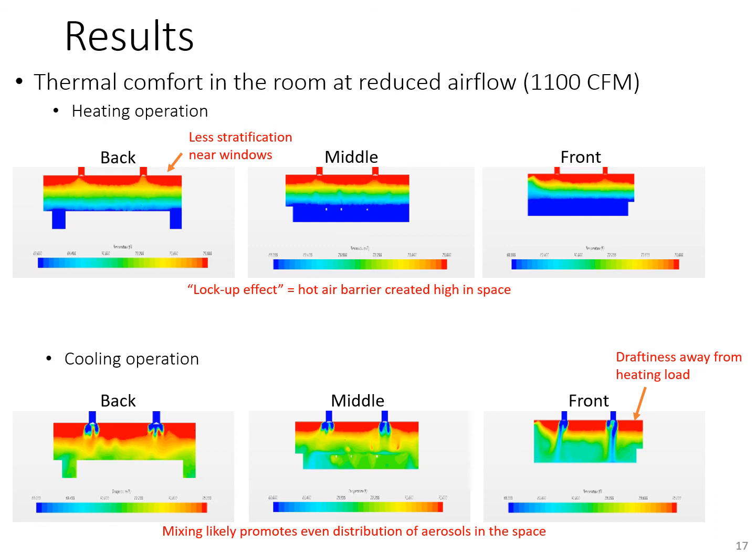First, the warm air of the space was not provided with enough CFM to reduce thermal stratification and push the warm air closer to the students. Thus, you would likely still have very cold zones near the students' legs and feet. However, interestingly, the thermal stratification appears to be reduced as you get closer to the exterior wall and windows in the back of the classroom, showing how the warm air tends to flow toward the locations of heat loss.